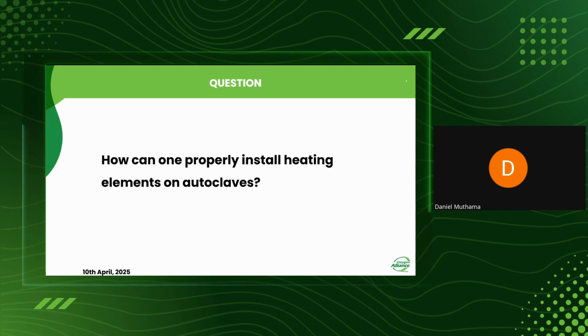Then you connect two terminals of other elements and supply with the blue line. At that time, you have balanced the phases. The other remaining terminals of the elements, you interconnect all of them and supply the neutral connection. That's how you supply the electric heating element, and that's how you balance the three-phase supply system.